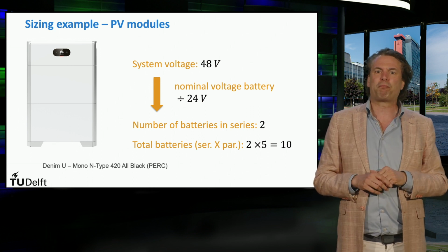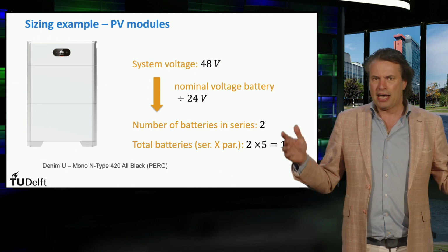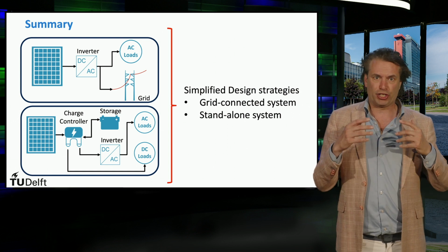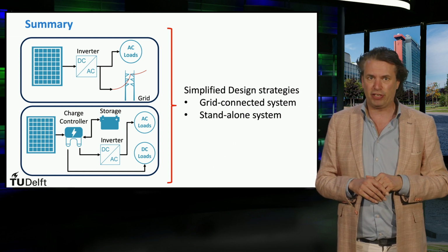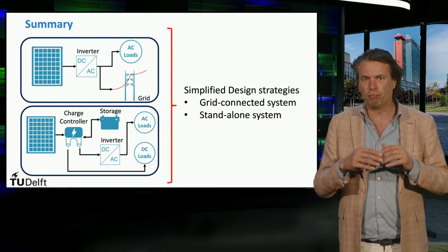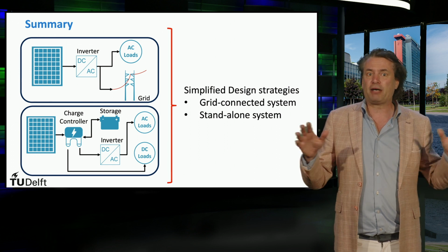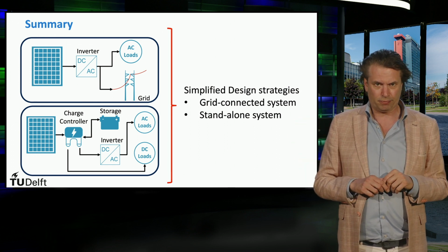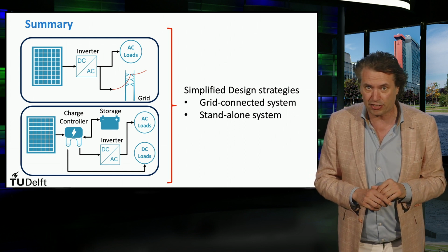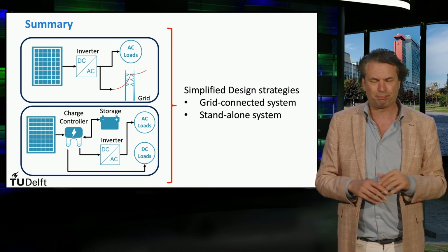You will be able to practice more on this in the exercises of this week. In summary, we have discussed a simplified approach to design and size a standalone PV system based on the load needs, the local irradiance data, the specs of the modules, inverters and batteries. An overview of all steps is summarized in a handy table. Please note that a PDF version of all the design steps of this simplified design strategy will be made available to the students for their reference on the platform.